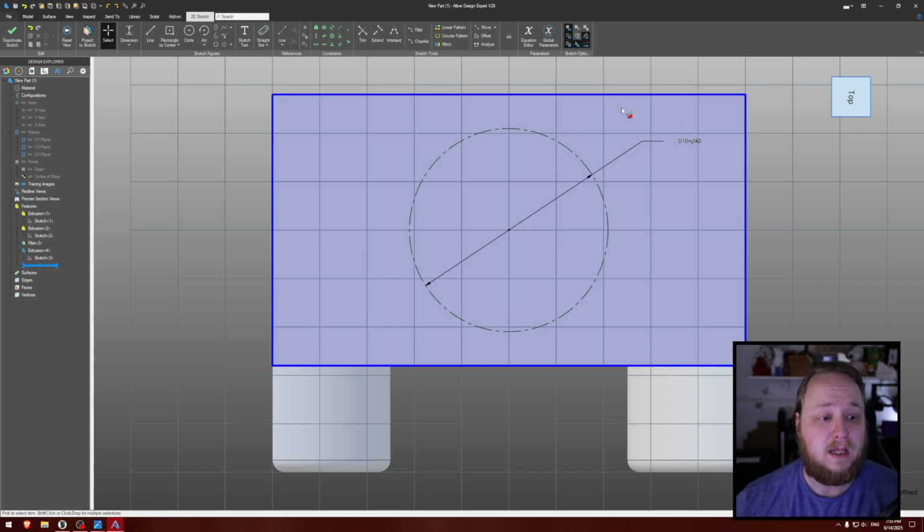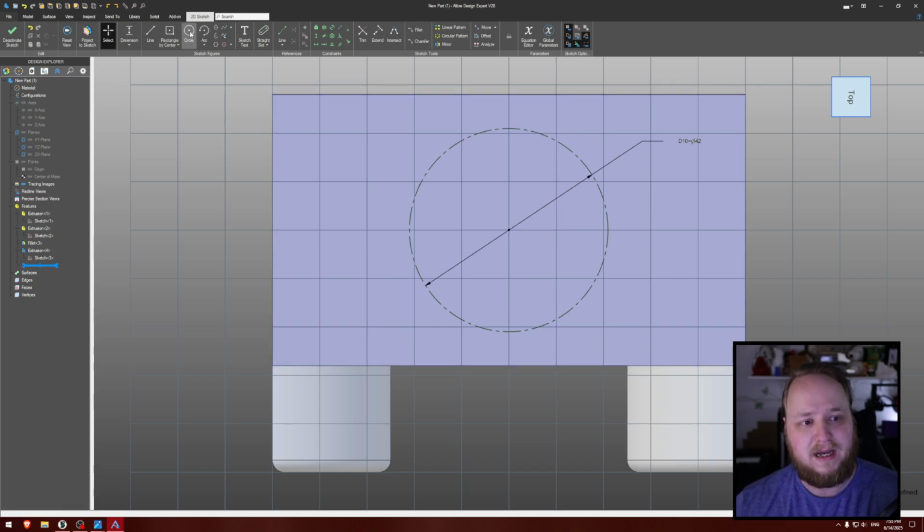From here, let's do a circle tool again. And let's go ahead and, if you hover your mouse, it's going to give you that little red line that tells you you're vertical with the origin. Let's go ahead and finish that off and use the dimension tool to make that 4 millimeters. And let's tell it that we do in fact want that vertical with the origin. Our vertical constraint is here. Please use a keyboard shortcut. And now we're all fully constrained.